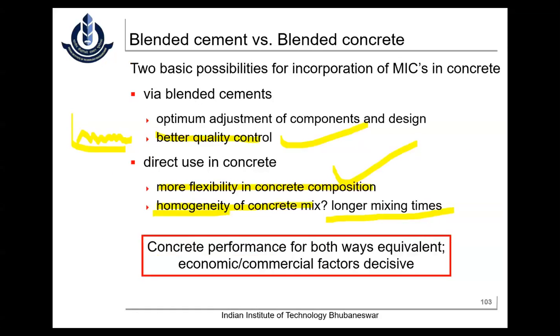In fact, just to give a brief overview, you had given the qualitative advantages of using blended cement, and at the same time how much environmental contribution that leads to, because for every kg of blending material that we use, that much CO2 is avoided. That is one of the most important aspects as far as the environmental parameter is concerned. But more importantly, the qualitative factors in terms of enhancing durability, reducing leaching, and lowering heat of hydration, you had explained very well.